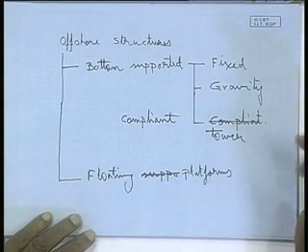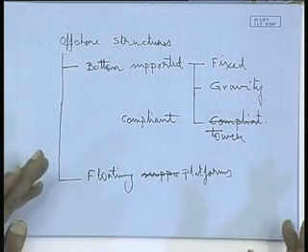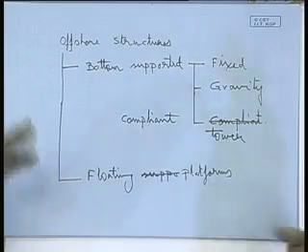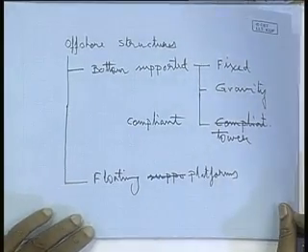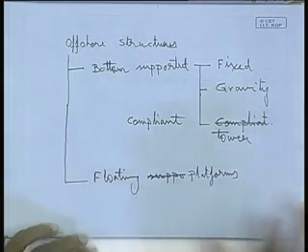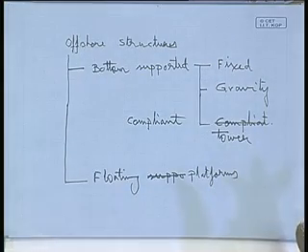Still, with the requirement of further depth, then came the concept of floating platforms. The moment it became a floating platform, it became absolutely free. You do not have any restrictions of what the subsoil condition is, and virtually no restriction of what depth you are going to operate in, right. In floating platforms, we have two types.